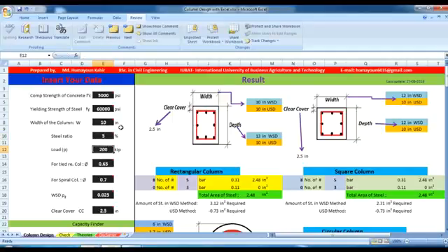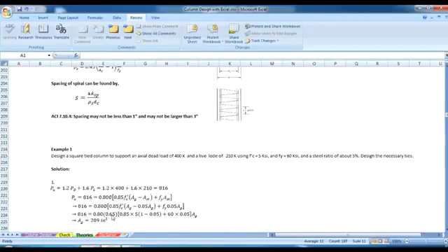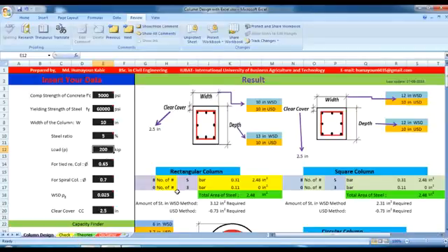Then the loads, let's go to the theory step for loads. Dead load is given 400 kip and live load is given 210 kip. Because of the code, we need to multiply 1.2 with dead load and 1.6 with live load. After adding these two loads, we will get a factored load. So it's done here. The factored load is 816 kip. So let's put this value on the column design tab. 816 kip.